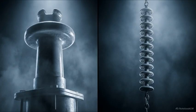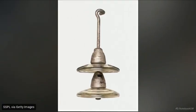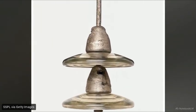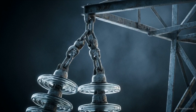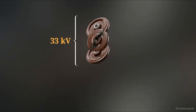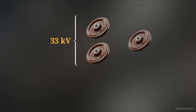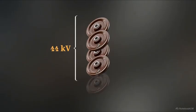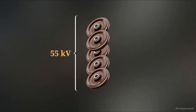Instead of making the insulators bigger, engineers moved to a modular design, the suspension string. This setup uses a series of individual porcelain or glass discs linked by metal pins to form a flexible chain hanging from the tower's arm. This modularity allows for easy maintenance. If one disc breaks, you only replace that unit. More importantly, you can handle higher voltages simply by adding more discs to the string.